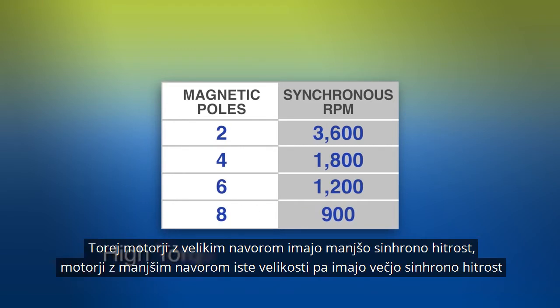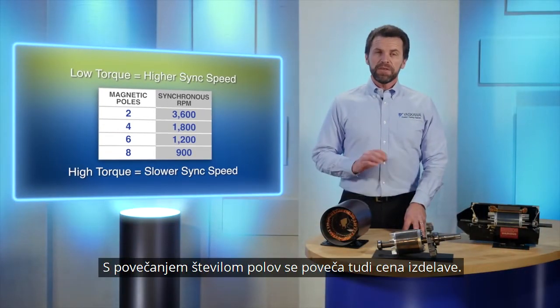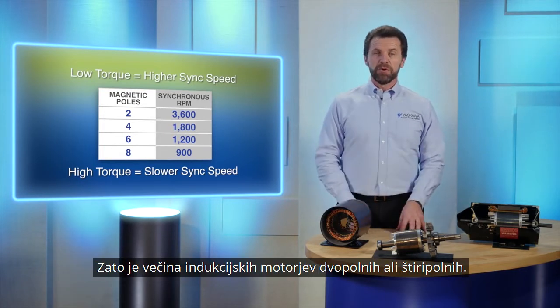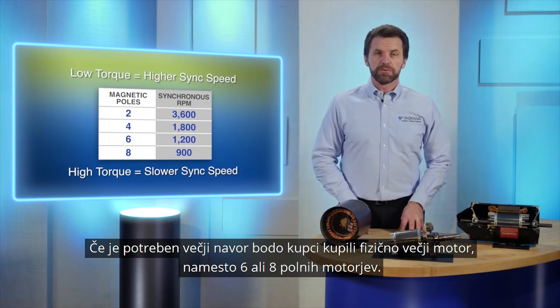So, high torque induction motors have slower sync speeds, and lower torque motors of the same size have less torque and higher synchronous speeds. One thing to note, as pole count increases, so does the cost of manufacturing. So most induction motors are 2 or 4-pole configurations. If more torque is needed, most people will opt for a physically larger motor instead of using a 6 or 8-pole machine.